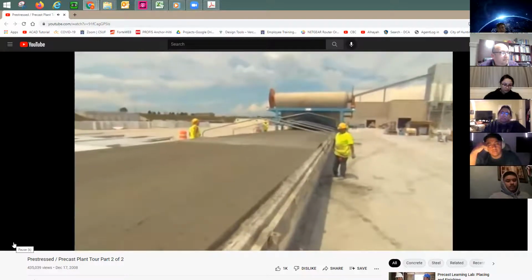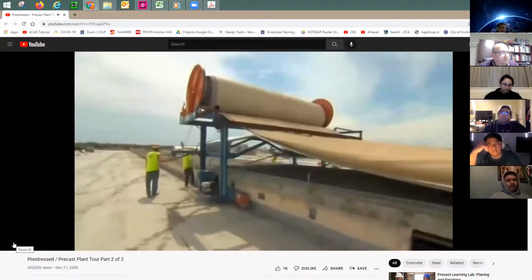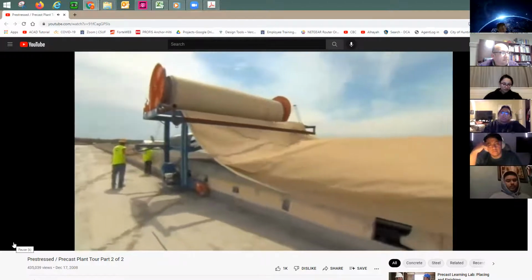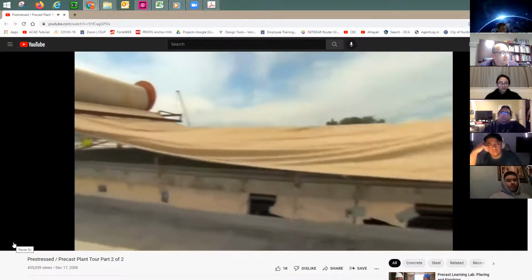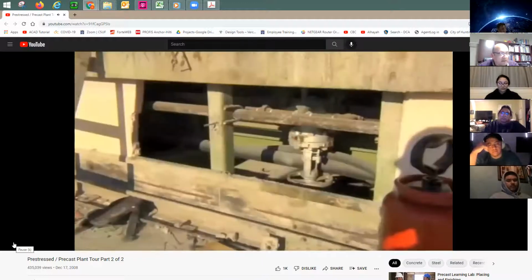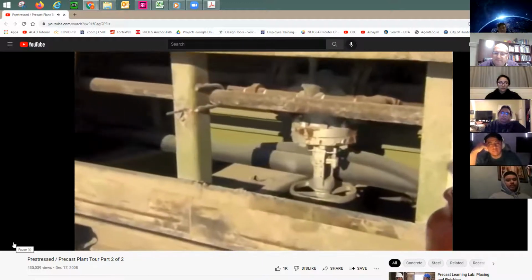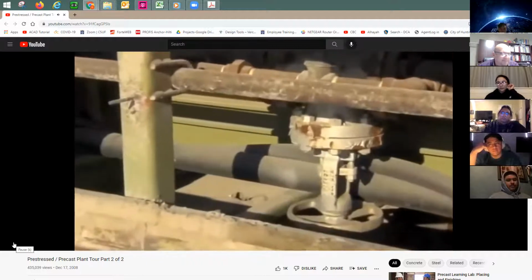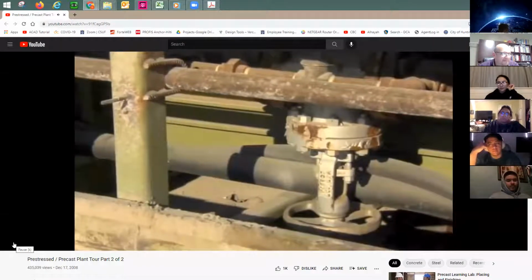The bed is now in its curing stage. Sometimes, particularly in cold climates, the double T may be covered with tarps. In other areas, they may be open. This is a good size curing tarp. Accelerated curing is often done using live steam or radiant heat from heaters attached to the form itself.